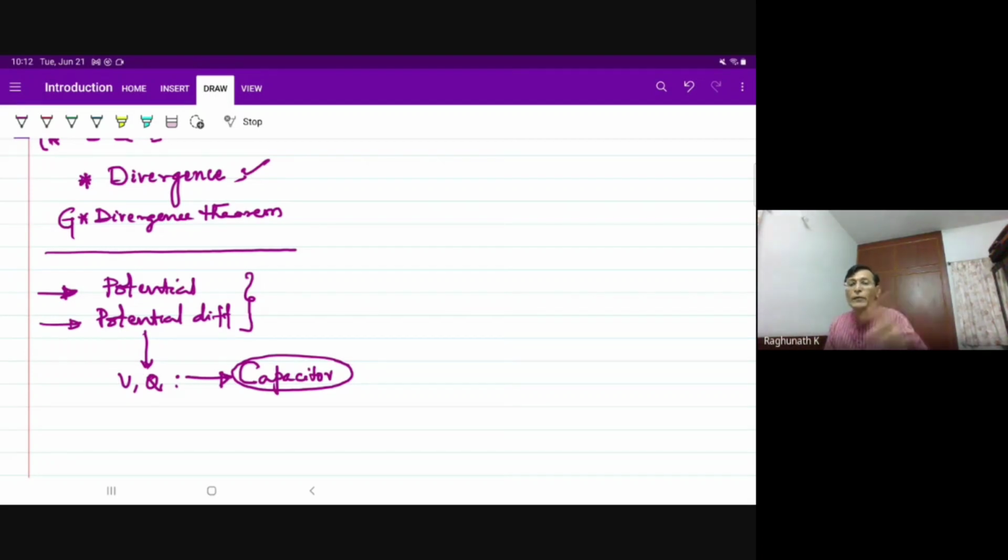And if somebody gives you the dimensions and medium, you immediately calculate the capacitance. And this capacitance calculation between the conductors, a bit higher level if I want to go. People really struggle a lot here. Many people sit together, do the job of SPICE monkeys, and then SPICE monkeys what? Trial and error. Millions of trial and error operations they do and ultimately fix the component values, not by using the design formula. They develop an IC like that. When they develop an IC like that, different components are to be interconnected through a layout.